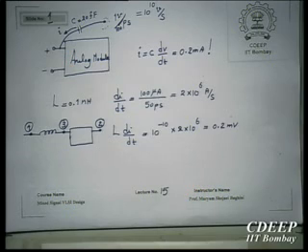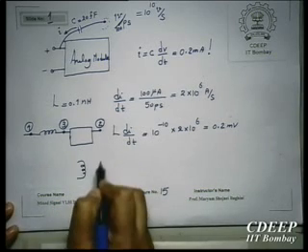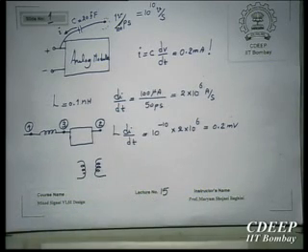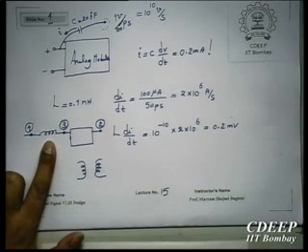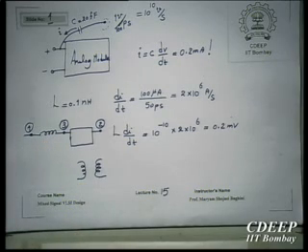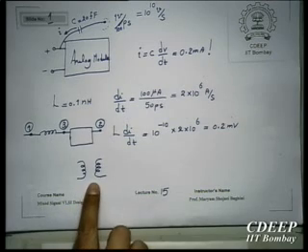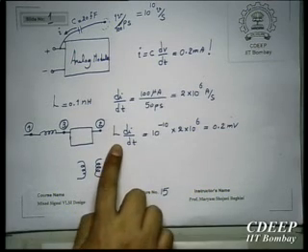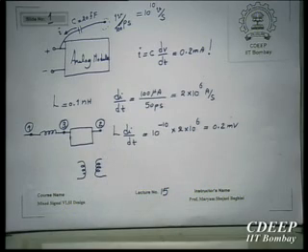If you have two loops, then you are talking about the transformer effect. Yeah, that is different from what I'm talking about. I'm talking about this effect, okay? You have a single inductor in series in a branch. Capacitance is parallel, inductor is in series. The effect is like that. Yeah, that is also possible. But actually, this mutual inductance is even less. Otherwise, everybody could make a solid state transformer. That is one of the reasons it's very difficult.